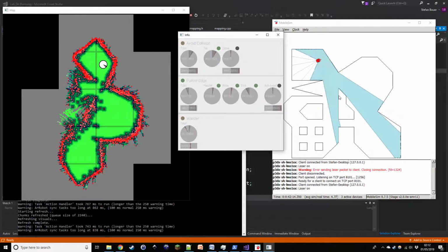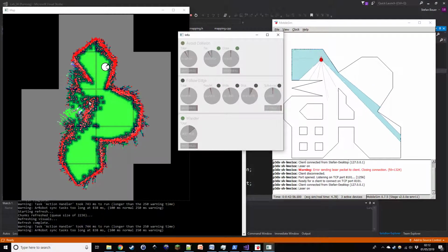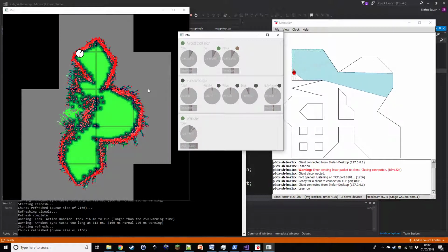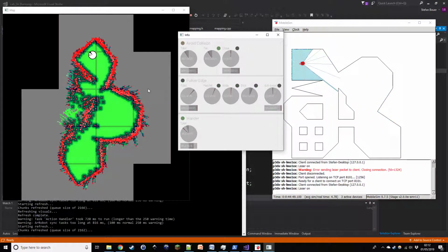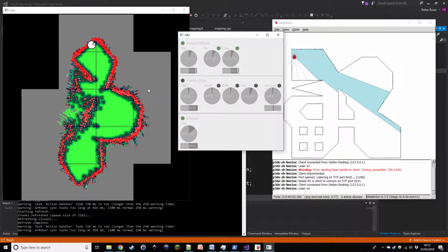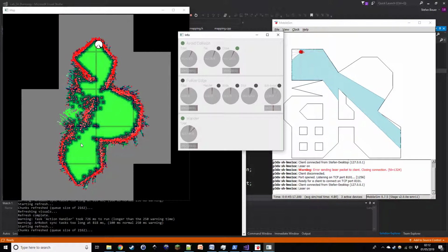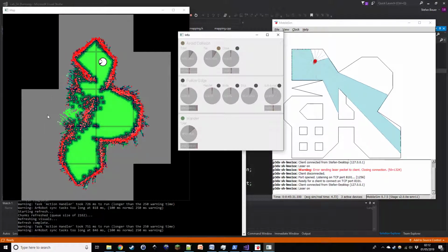The most major problem I've found is just that the resolution on the sonars is terrible, and they seem to have an awful lot of noise, as is clearly demonstrated on the map. I don't feel like that's an error on my part. That's my code functioning as intended. And as could be expected, it's simply that the sonars pick up a lot of incorrect readings. And as I said, I've done my best to kind of denoise the map as I go along by detecting that sonars are going through tiles that had been marked as empty. But even so, it just creates a horrible mess, and that's slightly annoying.